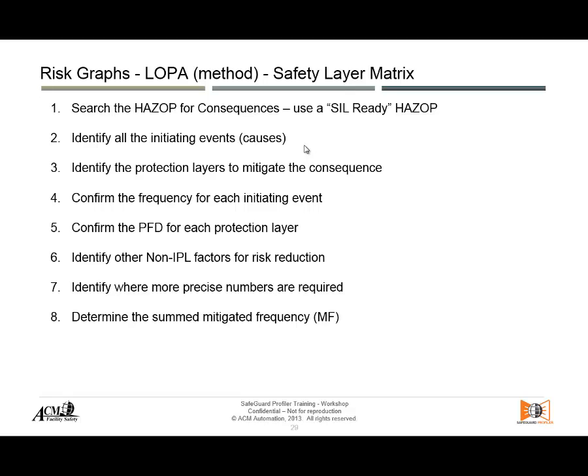That means that sometimes one layer protection analysis scenario contains more than one HAZOP scenario. And the commonality between them is that they all lead to the same consequence, the same severity, and they are all in the same area or the same unit, right? So that means there is risk coming at you from different deviations, different causes, and they all have to be summed up, right?